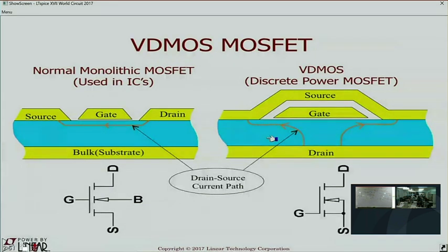Okay, now the Miller capacitance is the capacitance between the gate and the drain. And it's due to electric field lines through here, and these electric field lines don't particularly bend independent of whether the channel is conductive or not. So this structure has the same gate drain capacitance independent of whether the transistor is on or off. That's not the deal over here. See, the channel is in between the gate and the drain, and so if you turn the gate on, it's like that dielectric isn't there. You've moved the gate and drain parallel plate capacitance all closer together.